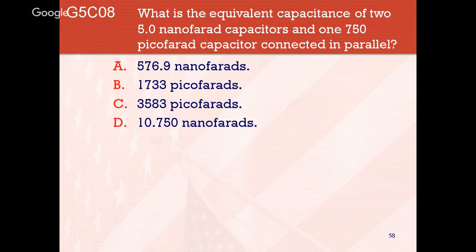What is the equivalent capacitance of two 5 nanofarad capacitors and one 750 picofarad capacitor connected in parallel? Remember what happens when you have capacitors in parallel, unlike resistors that are in parallel. Capacitors in parallel are like resistors in series. You're going to add those values together, and